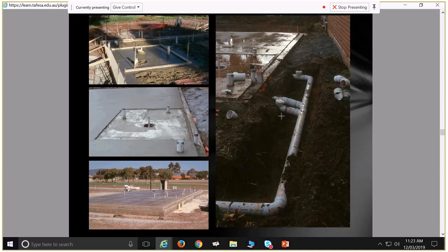For a puddle flange, you need 20 millimetres of screed contacting with that puddle flange. So you have to add 20 millimetres to the height of your distance there as well. So if we had our 4 metre bathroom, and we're planning on just having our shower as a drain for that, we need to have our 20 millimetres depth at our puddle flange. We have to have 50 millimetres of fall over that whole distance. That means we have to have 70 millimetres of set down just to produce that screed.